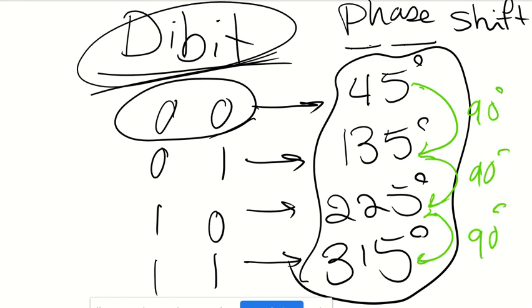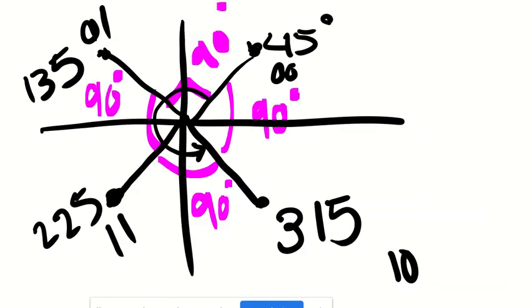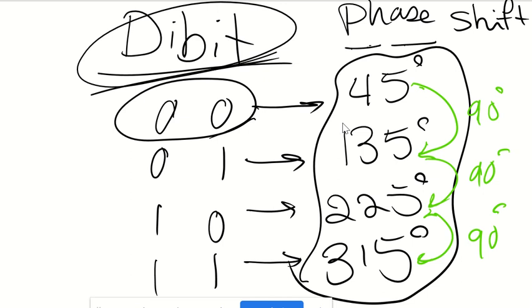So again, what I did for QPSK, instead of changing the phase for one bit of information, as I said, you can increase the number of bits. Here I'm showing you 2 bits of information. For 2 bits of information, I am changing the phase accordingly. And this is all the combinations I can have. I cannot have anything other than what I wrote here. So 1, 0.